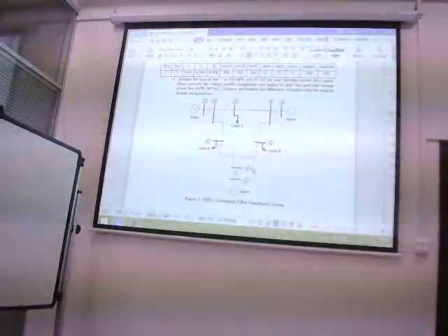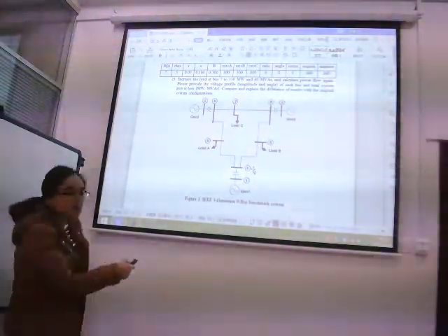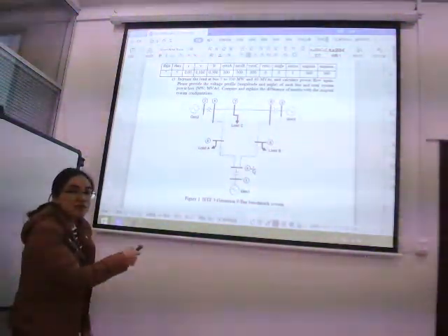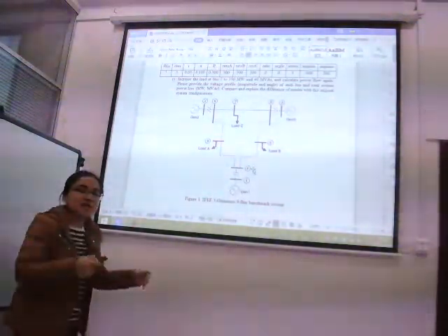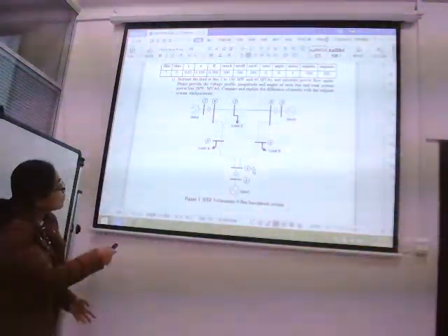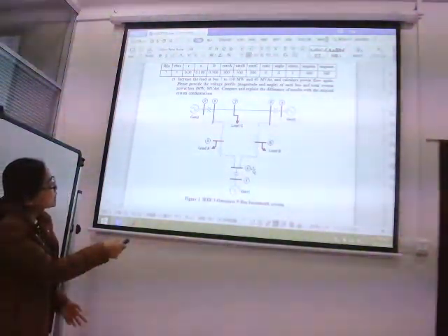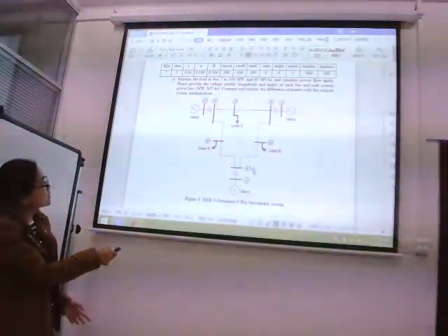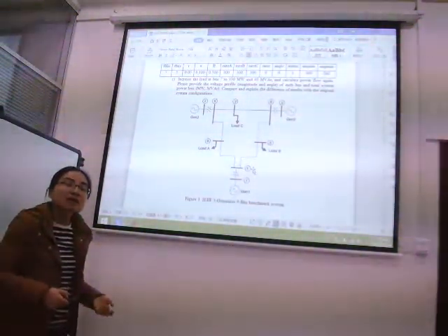Then the load demand in bus 5 is supplied from bus 7, because bus 7 has enough power. It can also transfer power here. So we don't need to transfer power here from generator 3 to bus 5. Then the power loss is decreased. Is that clear?